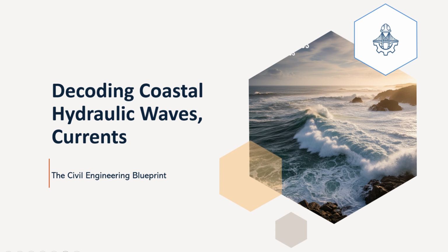The first term is the familiar hydrostatic pressure, -ρgz, if z is positive upwards. This component is always present, regardless of waves, and it increases linearly with depth below the still water level, SWL. It's just the weight of the water above. The second term is the wave-induced hydrodynamic pressure. This dynamic component exists only when waves are present. It comes directly from the time-varying part of the velocity potential.